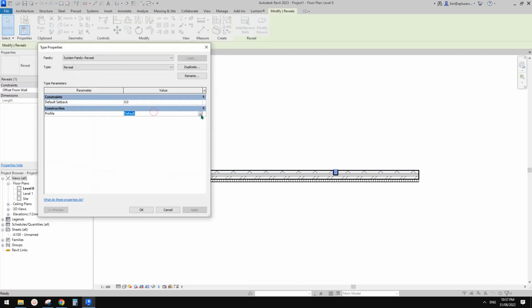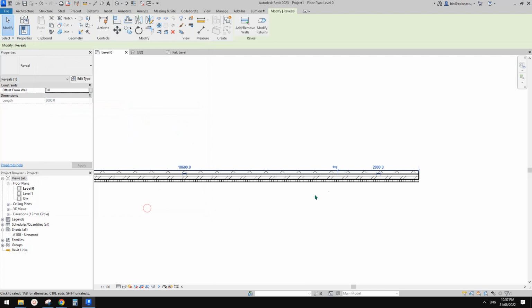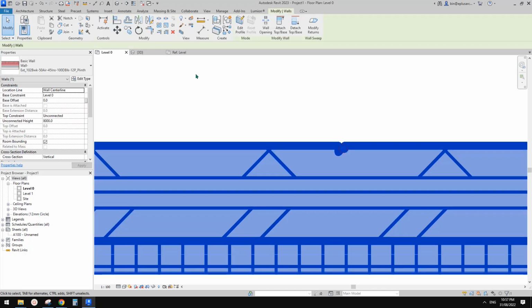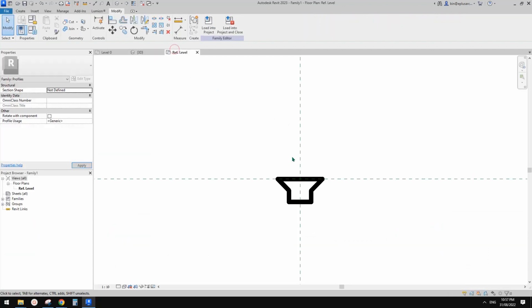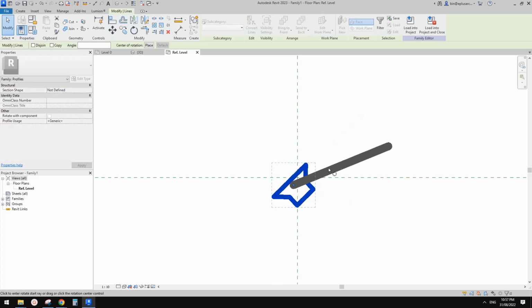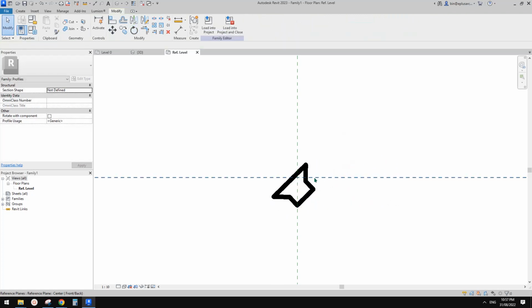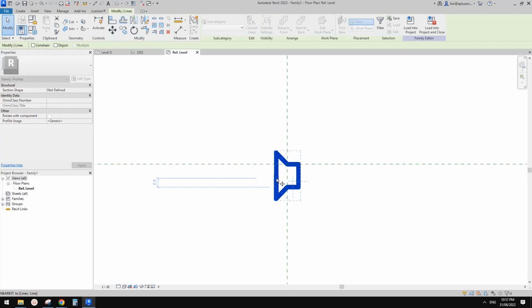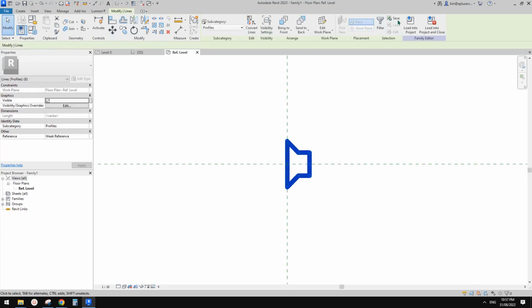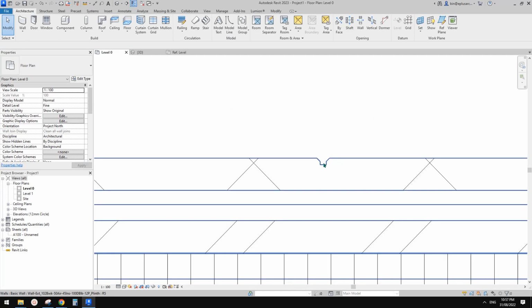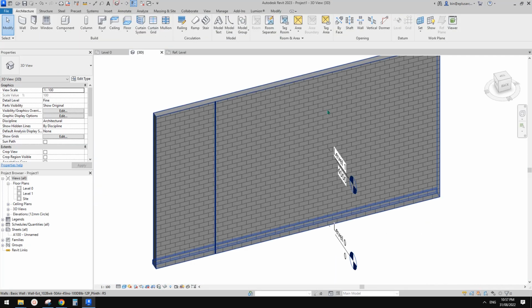I'll just change this reveal to this one. Okay, so you can see the direction is wrong, sorry. It needs to be rotated by 90 degrees. Oops, sorry. Control Z, RO 90, and MV, move this point to here. Load this back, overwrite. Yeah, that's better. So you can see it creates a reveal, a gap.